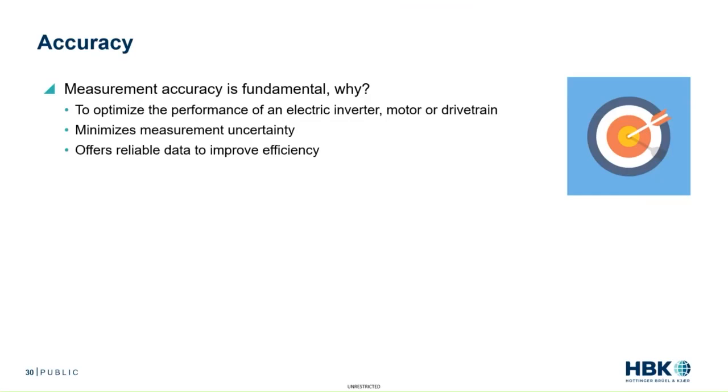Selecting a power analyzer with the best base power accuracy available is an investment in the long-term future of your products and your solutions. So you also want to make sure you select a power analyzer with the best torque and speed accuracy. So not just the voltage and current inputs, but also the torque and speed, especially with the ability to use digital frequency signals for noise immunity instead of just trying to capture an analog torque, which often has a lot of noise involved. So you'll need to identify the accuracy of the timer counter inputs on a power analyzer.